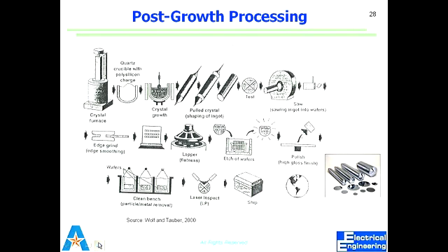We do use both side polished as well, but that is a technology which is used in industry. So industry uses both sides of the wafer. They don't want to miss any semiconductor material to make devices. So they are double side polished. And there is a special type of those wafers. We'll look at those. They are called SOI, silicon on insulator wafers, which are double side polished.